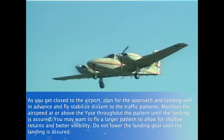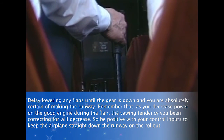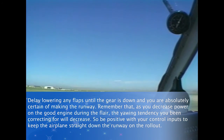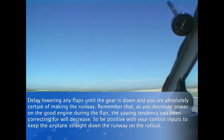Do not lower the landing gear until the landing is assured. Delay lowering any flaps until the gear is down and you are absolutely certain of making the runway. Remember that as you decrease power on the good engine during the flare, the yawing tendency you've been correcting for will decrease. So be positive with your control inputs to keep the airplane straight down the runway on the rollout.